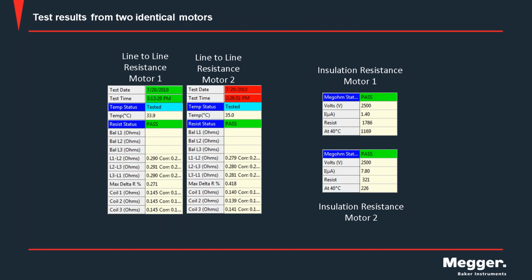So we didn't have any trendable comparisons, no time trends, but we were able, because they were exactly the same design, to make what I call a comparison of like design. So we're trending by comparison in this case, and looking for deviations. And so you can see, here's a spoiler alert. We got something that's red, but it's not resistance. There's a slight difference in resistance here, but it's not significant.